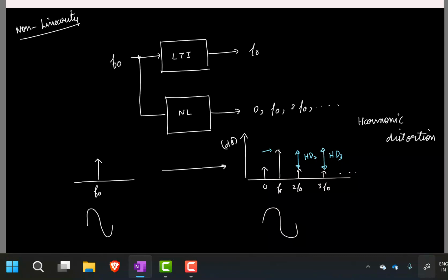Power supply. Yeah, basically from the power supply, it takes a fraction of the DC power and converts it to some other frequency, right? So here you see there is an inherent frequency conversion, and that is not possible if you just have a purely linear system. Only if you have a non-linear system like this, you can have frequency conversions, and only then amplification itself is possible. So you need non-linearity for power amplification, but you don't need so much of non-linearity. That's all. So it is like food, right? You need food for absolute survival, but a lot of food is also not great, right?